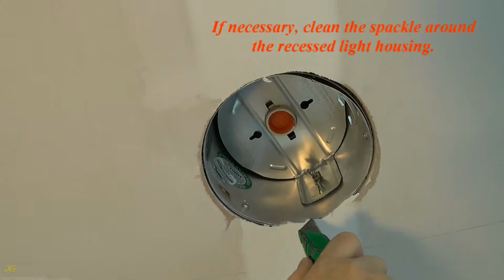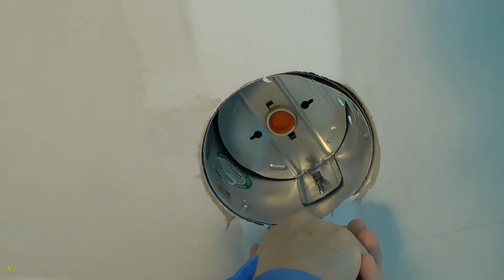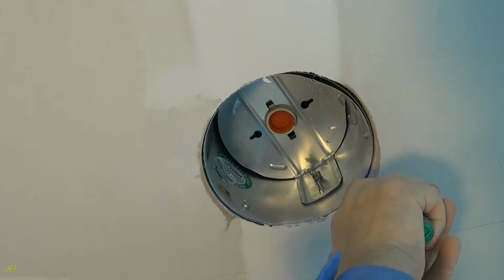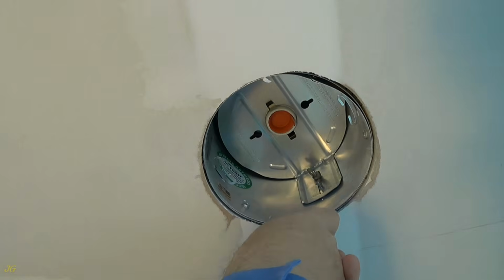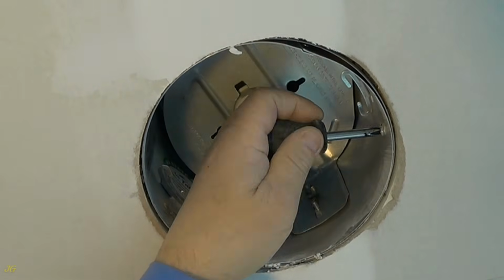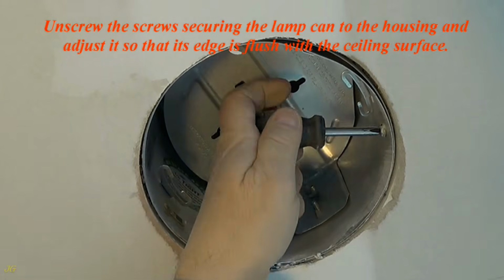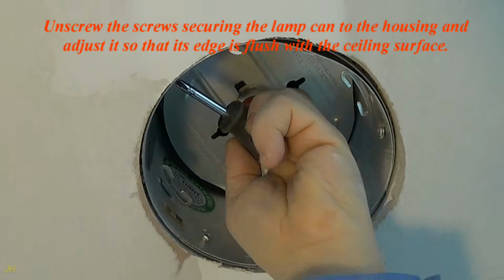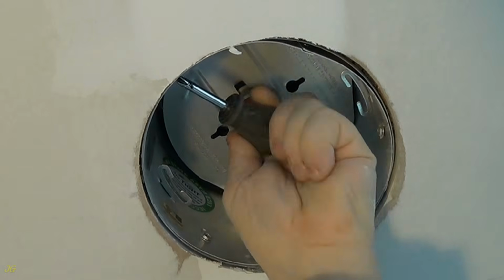If necessary, clean the spackle around the recessed light housing. Unscrew the screws securing the lamp to the housing and adjust it so that its edge is flush with the ceiling surface.